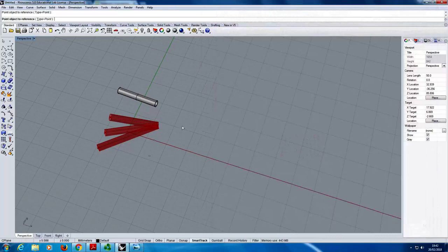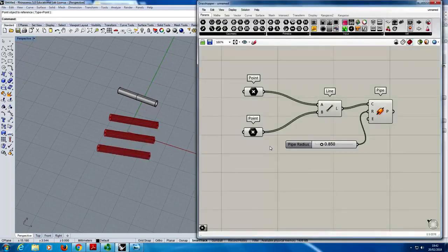So now let's set multiple points and select those 3 points. So now, well, before you do that, just have a think about what you actually expect the output from this to be. Because there's several different ways that Grasshopper could interpret this. And if we left click on each one of those and hit return, we'll see the way that Grasshopper does actually deal with that. So what's happening now is we've got 3 points coming out from that component and 3 points coming out from that component. And what this component is doing is something which is very important to understand in Grasshopper, that's called data matching.